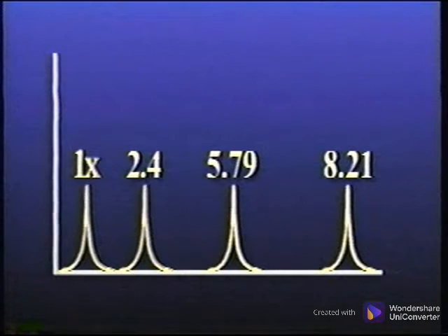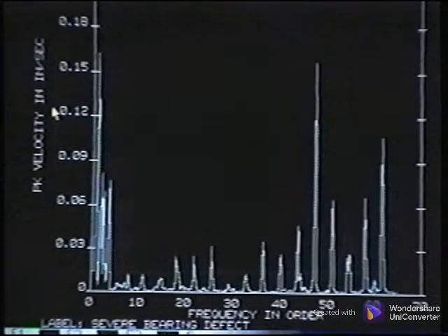However, these primary defect frequencies may be so low in amplitude that they are not even noticed by the analyst. Instead, it is multiples or harmonics of these defect frequencies that tend to show up first in the high-frequency range of the spectrum. Knowing this, we need to be very specific as to how we display spectral data. This spectrum is displayed in velocity, which allows us to see this high-frequency energy as well as the low frequency of 1 times and even subharmonics.